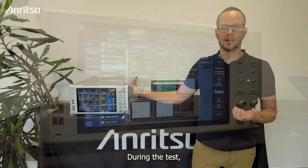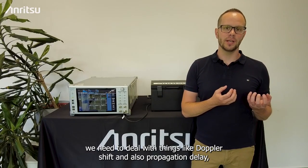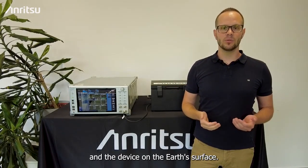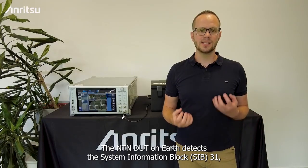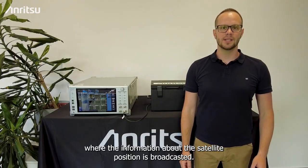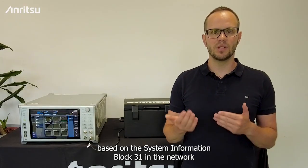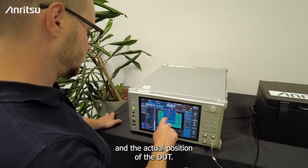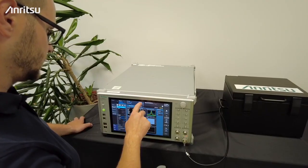During the tests, we need to deal with things like Doppler shift and also propagation delay, which is caused by the distance between the satellites and the device on the Earth's surface. The NTN DUT on Earth detects the System Information Block 31, where the information about the satellite position is broadcasted. The delay between the satellite and the DUT is calculated based on the System Information Block 31 in the network and the actual position of the DUT.